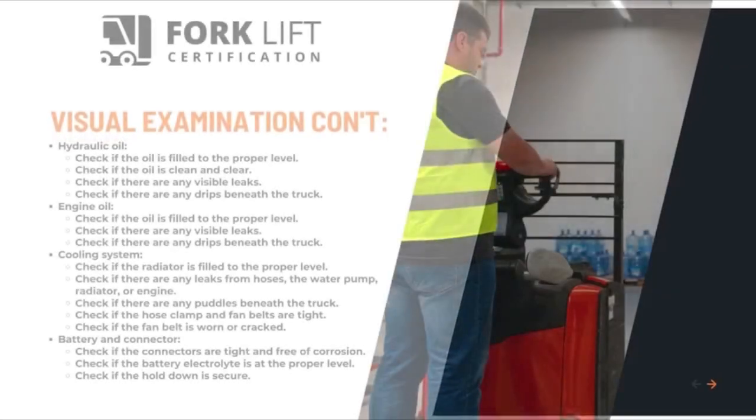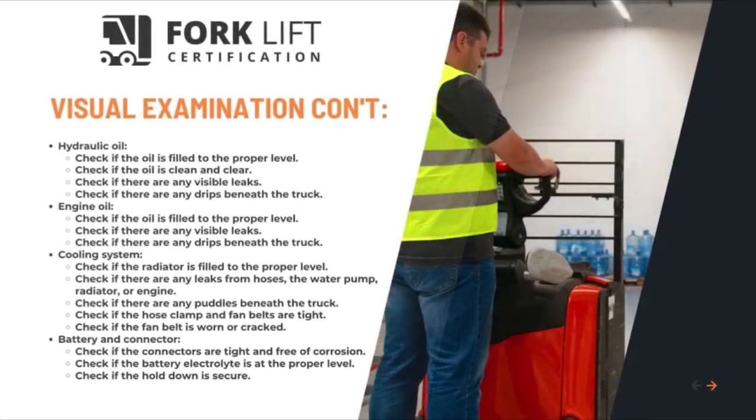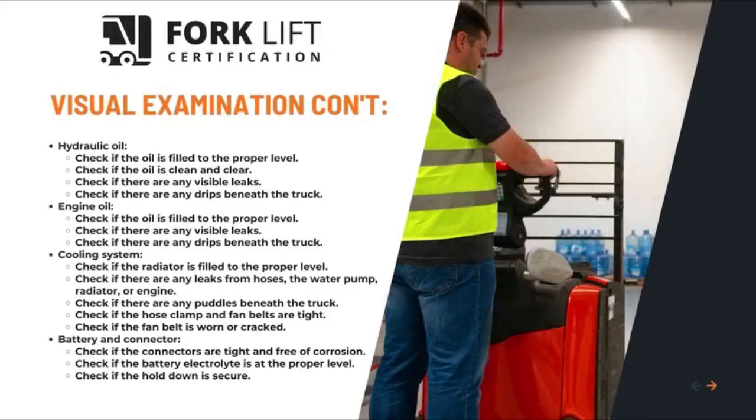Hydraulic oil. Check if the oil is filled to the proper level. Check if the oil is clean and clear. Check if there are any visible leaks. Check if there are any drips beneath the truck. Engine oil. Check if the oil is filled to the proper level. Check if there are any visible leaks. Check if there are any drips beneath the truck.